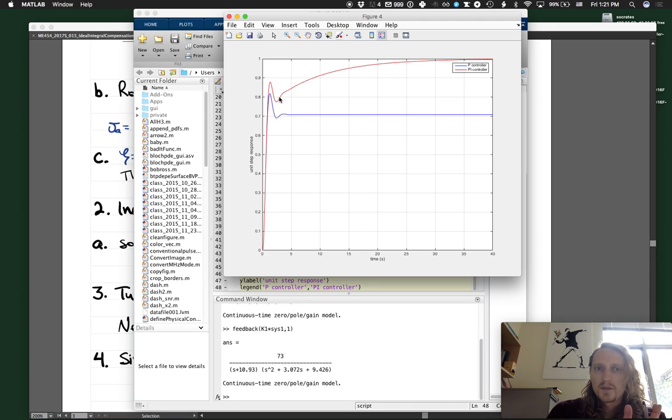The same transient response, essentially that little overshoot and coming back. And then instead of settling out to a steady state error of 29%, the integrator kicks in and it brings it up to approximately 0 error, or 0 if you were to go to infinite time. So that is a PI controller design. And that was just sort of a first whack at it.